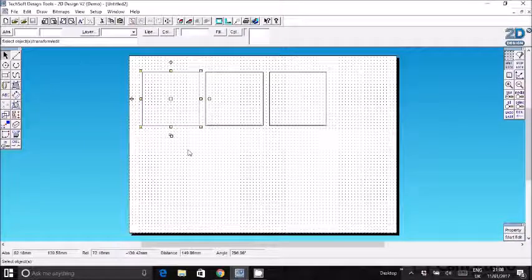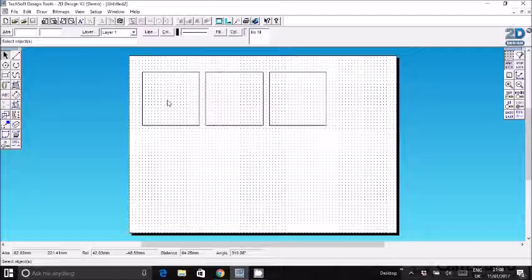Right, I think the first one we're going to do is a simple Bauhaus image. We'll do Bauhaus clock face here. So if you get this line tool, click the line, okay, and I want you to cross from the center, the top left to the bottom right, and then click the top right to the bottom left. Now that's giving me the dead center of my clock face. What I'm going to do is put a little hole there so I know where to drill.